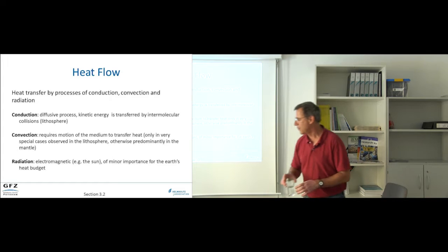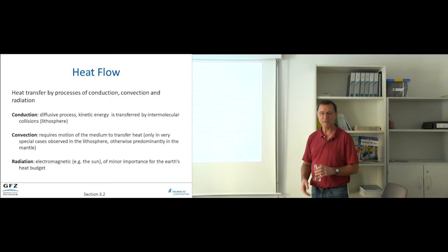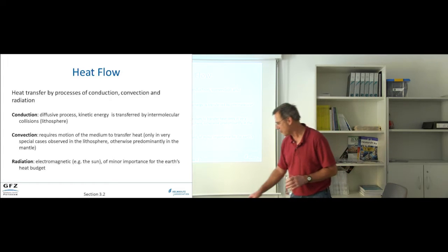The main heat transfer process in these packages always is conduction. Convection is really not a significant part in these packages because resolution is inadequate also with respect to time, because conduction is a relatively slow process. You can handle this quite nicely in the project. In the simulation, convection would be a very short-term process which would increase your calculation time significantly, and at least it's not considered to be the most significant process on this scale.